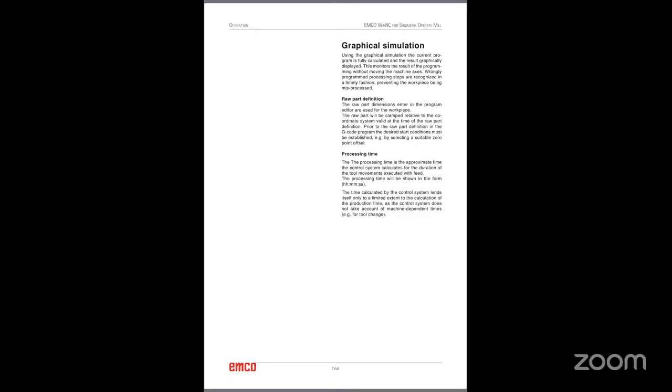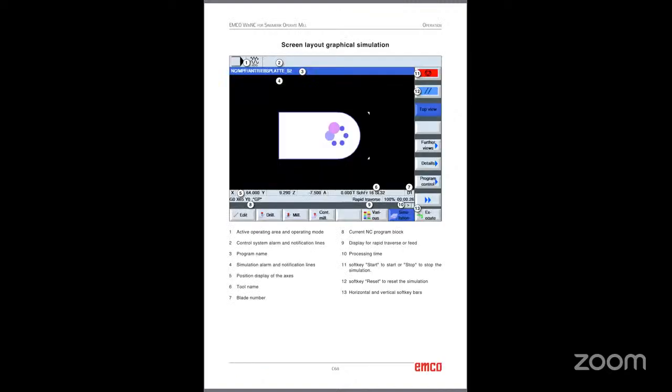During the simulation, the XY axes will not move. The spindle will not rotate. The tool will not touch the workpiece. Everything we can see on the screen only. But before starting the simulation, you should define the size of the raw material. For example, if you are using an aluminum block, what will be the length, width, and height?